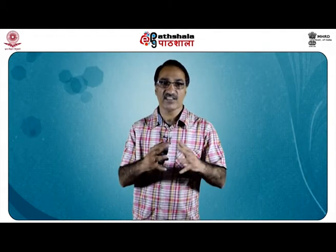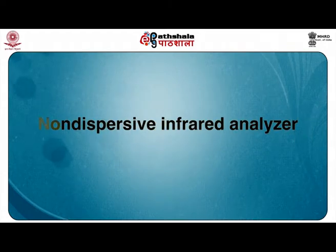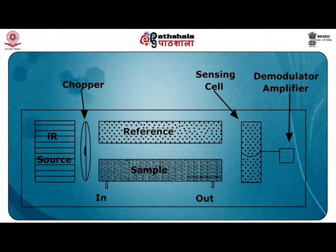Carbon monoxide has a characteristic infrared absorption near 4.6 micrometer. The absorption of infrared radiation by CO molecules can therefore be used to measure CO concentration in the presence of other gases. It is based on the fact that carbon monoxide, or CO, possesses a dipole moment which absorbs infrared radiation. Non-dispersive infrared analyzer. The non-dispersive infrared analyzer is made up of a sample cell in which a sample of